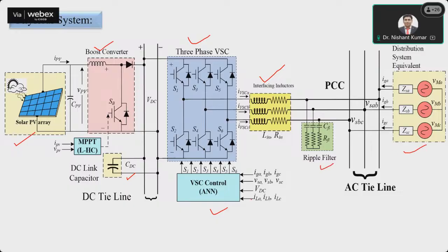So in this entire operation, I'm not talking about the digital twin, simple operation requires some additional sensors also. So what are those sensors? Grid current, grid voltages, DC link voltage, and then suppose we have a load, the load currents will be required. So the loads will be on the AC side. So these are the loads. The load current will also be required.